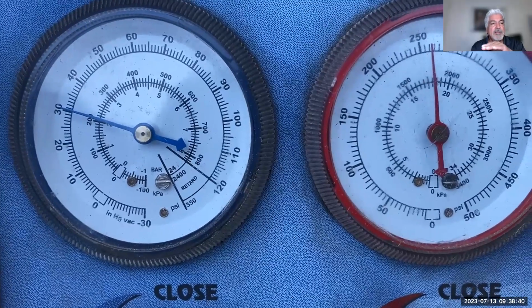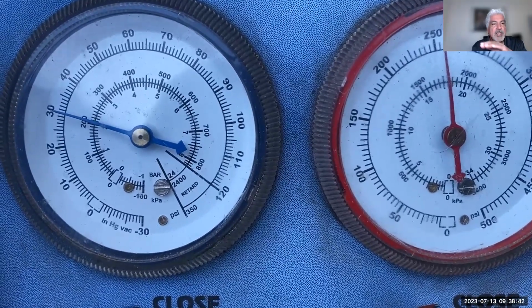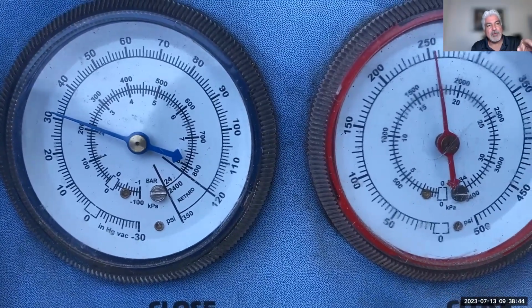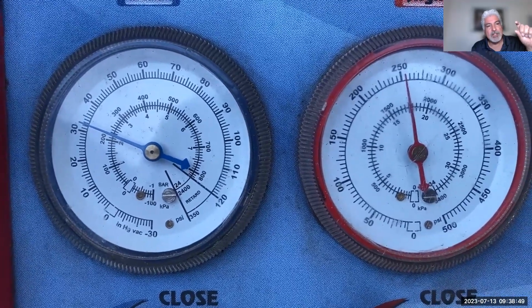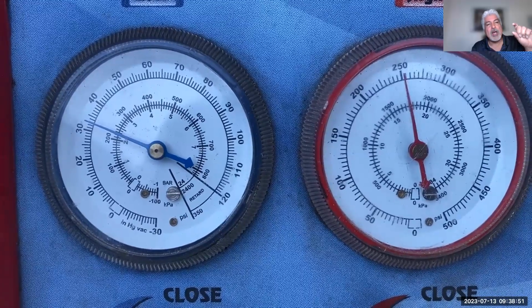This vehicle is a TDI VW I did yesterday. And you can see that again the pressure rises, the restriction, the ball valve closes. The ball valve opens a little bit, then closes. So it's varying, monitoring that outlet temperature.